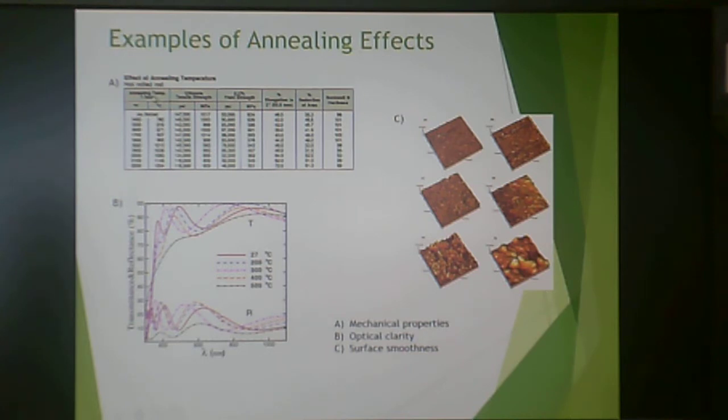So this is annealing temperature at 1 hour, and so here's 760 Celsius up to 1200 Celsius, and then the ultimate tensile strength. So if you held it at 760 Celsius for about an hour, you get up to about 760 to about 982, you get kind of the maximum tensile properties. You get better yield strengths, and you get more moderate elongation.